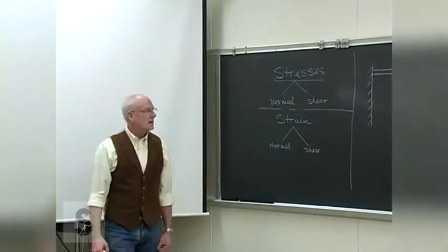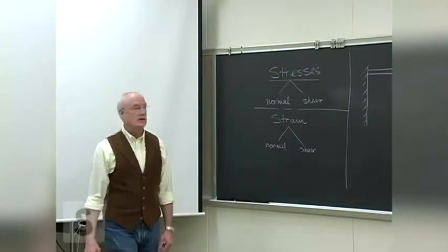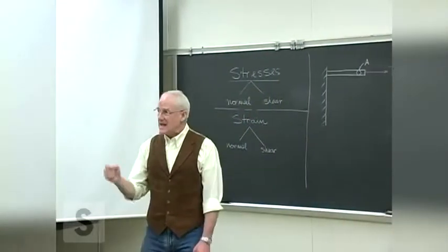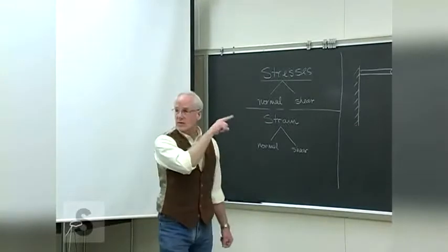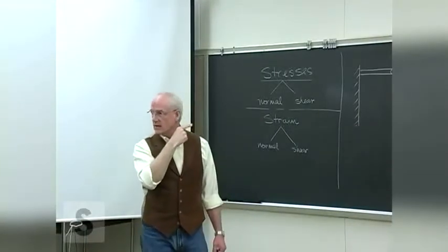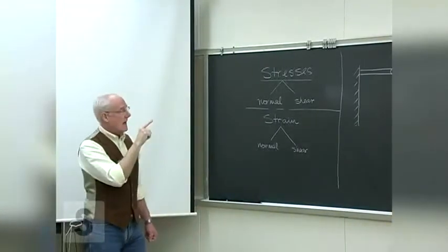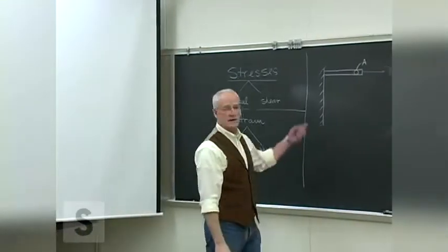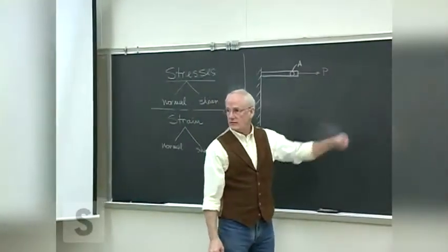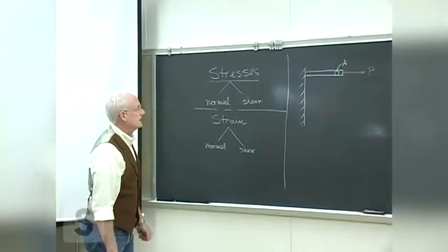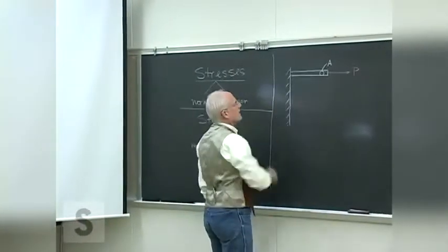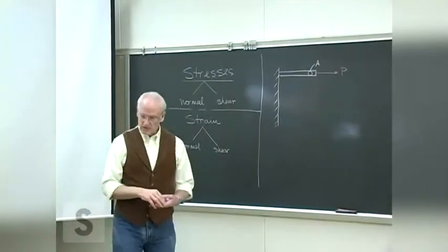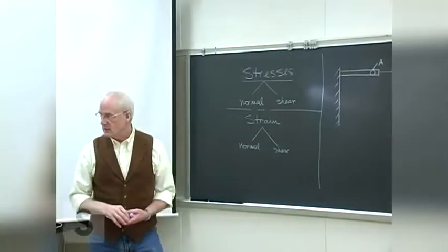Often that's entirely sufficient to then actually calculate that area as you need. So whatever the cross-sectional area is, as of yet we are not worried about what the shape is, we're just worried about what the area is. We'll find out very shortly how the shape of that area plays into it. We can have beams with the very same area and they're going to act very, very differently under loads, as we'll see. So we know that if we've got some member with some cross-sectional area under some load, that we could figure out the stresses in that piece.